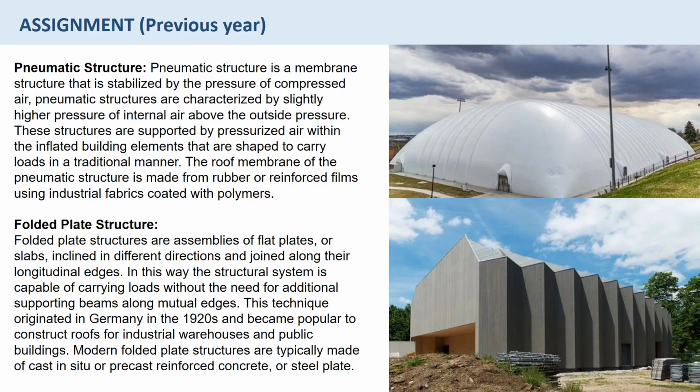Question 14. This image has been provided and you are asked to identify what kind of curvature this is: monoclastic, synclastic, anticlastic or bipolar. As explained in the previous question, monoclastic surfaces are single curved surfaces characterized by bending in only one direction at a time. In synclastic surfaces, the principal curvatures and the centers of curvature are on the same side of the surface. Anticlastic surfaces are those in which the centers of curvature are located on opposite sides of the surface.